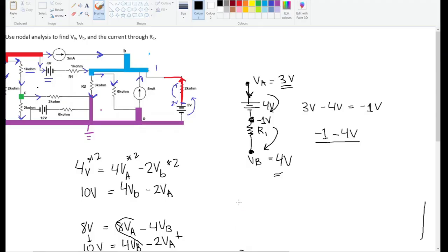Sorry, that's where I made my mistake. So you start off at negative 1 on the number line, right? And you went to 4 volts, which is the voltage of VB, right? So that much voltage change occurred across this resistor as you move through this resistor.